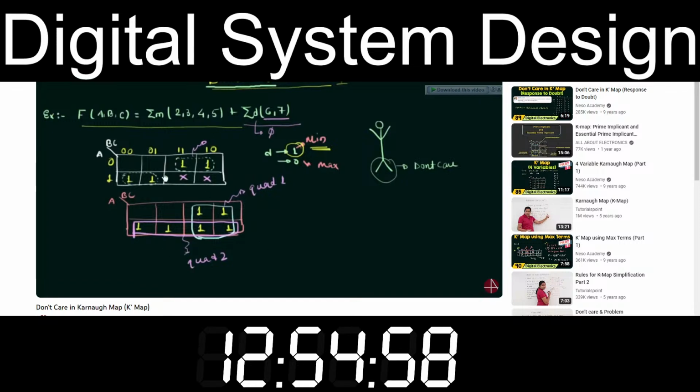Let's see how. For example, first let me write the function from this k-map. In this we are having A bar, and C is changing from 1 to 0, so C is neglected, and B is written as B because it is 1. Now or A, and B is 0, so it's changing from 0 to 1, so B bar. So A bar B or AB bar, this is actually your A XOR B.